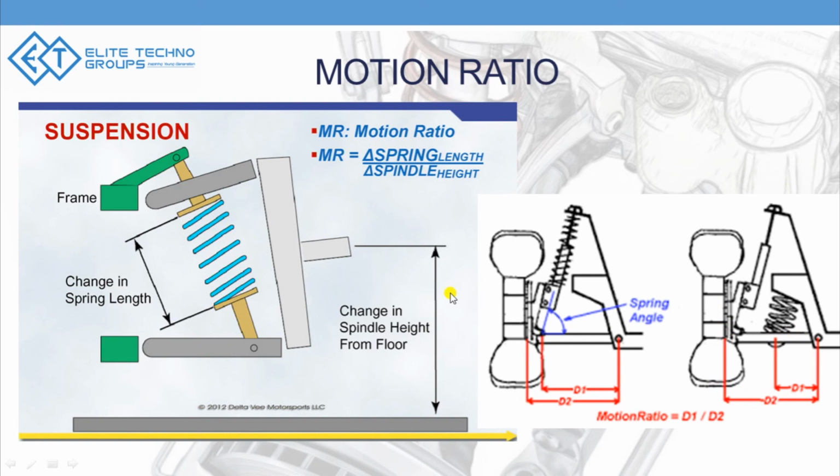How are these two actually one and the same? The reason is, if you think about it, this is going to be the axis along which your wheel is going to rotate, right? So if this moves by 1 millimeter, since the spring is attached closer to the pivot point than the wheel center, it will be moving a little bit shorter. So it's essentially one and the same thing. It's just where you look at that dimension from.